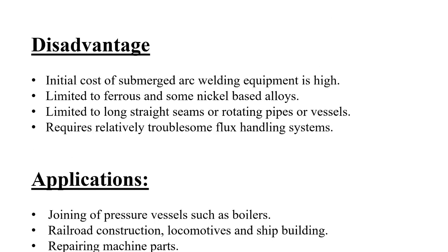Disadvantages: the initial cost of submerged arc welding equipment is high; it is limited to ferrous and some nickel-based alloys; it is limited to long straight seams and rotating pipes or vessels; and it requires a relatively troublesome flux handling system.